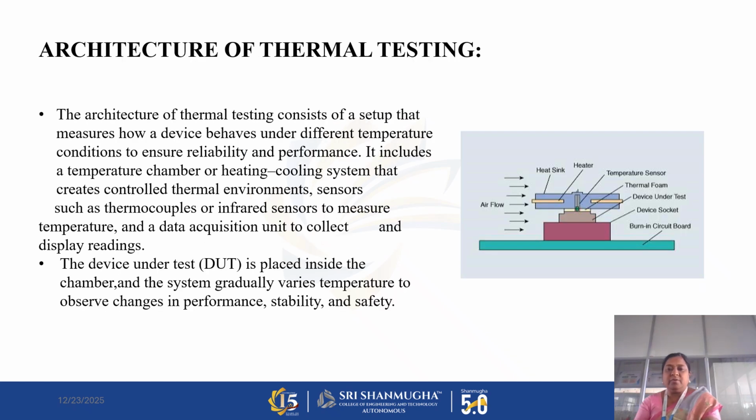This is the architecture of thermal testing. The architecture of thermal testing consists of a setup that measures how a device behaves under different temperature conditions to ensure reliability and performance. It includes a temperature chamber or heating cooling system that creates controlled thermal environments. Sensors such as thermocouples or infrared sensors measure temperature, and a data acquisition unit collects and displays readings.